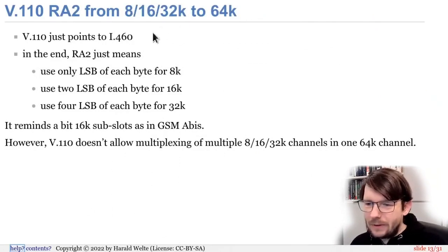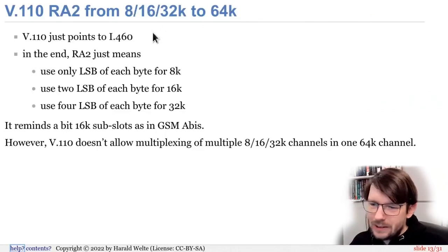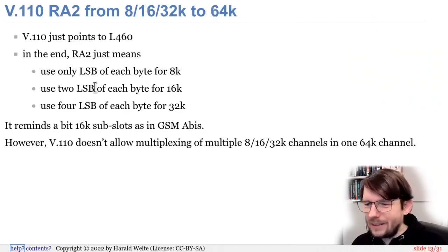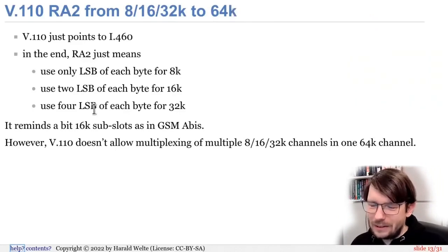It's actually not specified in V.110, but it just points to I.460, which is another ITU specification, which basically just means if we translate from an 8 kilobit to a 64 kilobit signal, we only use the least significant bit of each byte. And if we transfer from 16K to 64K, we take the 2 least significant bits, and if we go from 32K to 64 kilobit, we take the 4 least significant bits of each byte, and that's it.